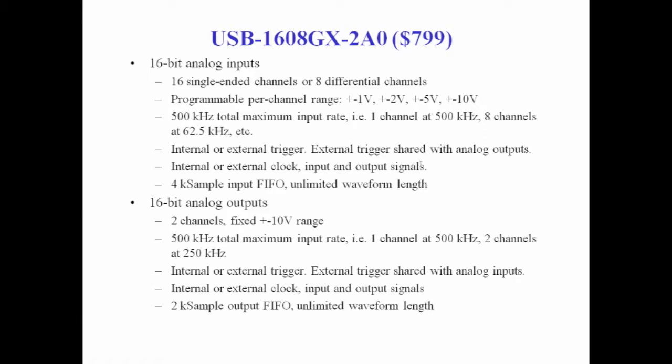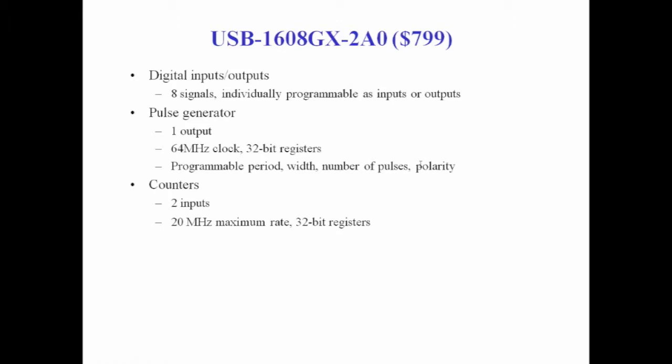Similarly, it's got two 16-bit analog outputs. Those can also be scanned, so you can load a waveform, and it will scan that waveform at up to 500 kilohertz. So it's like a programmable arbitrary function generator, or just simple analog output. Again, unlimited waveform length, because you just define it on the host and then it streams it across the USB. It's got 8 digital input-output signals, and they're individually programmable as inputs or outputs.